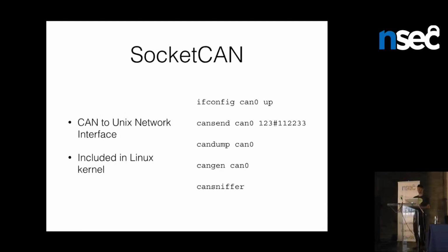Basically, this makes a Linux system, or any Unix system, look at a CAN device, whether USB to CAN or whatever to CAN, and makes it think that device is actually a network device. At this point, you can use the standard socket API and everything you'd expect with a normal network device. You can actually have raw CAN sockets. It's one of those things that people who have played around with sockets a lot have never seen, but it's there. And it's included in the modern Linux kernel.